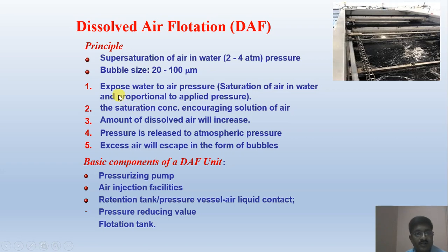Now, what are the various parameters? Water is exposed to air pressure, and the saturation of air in water is proportional to the applied pressure. The saturation concentration encourages dissolution of air, so the amount of dissolved air will increase. When the pressure is released to atmospheric pressure, the excess air will escape in the form of bubbles.